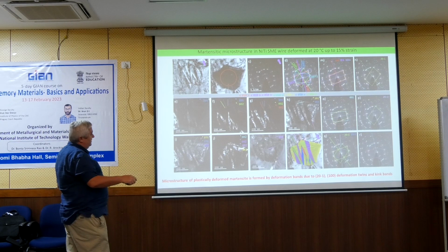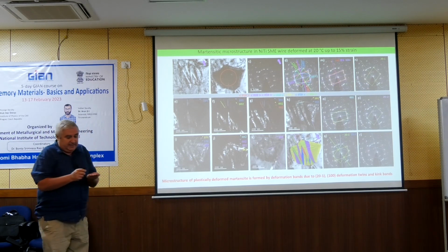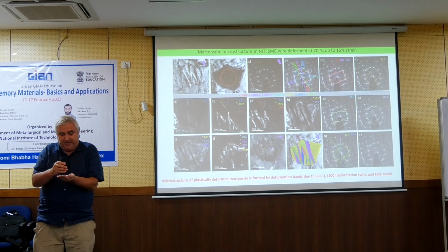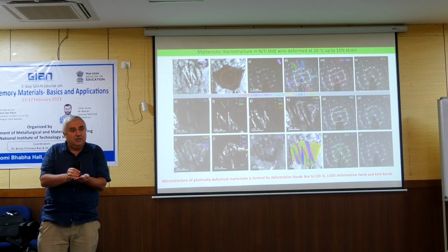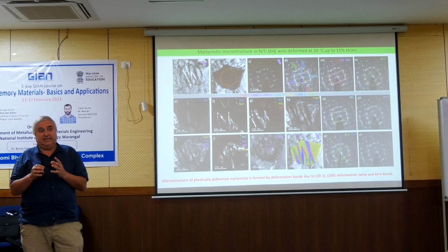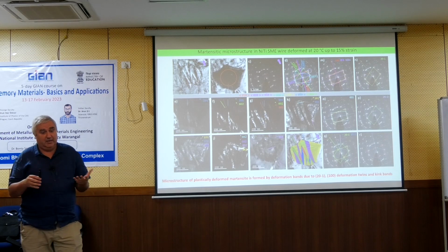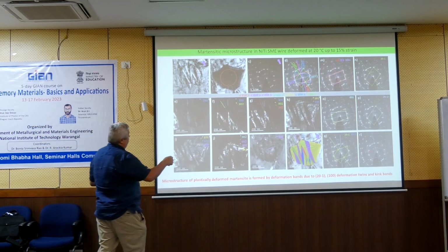So it means that if there are some bands, and there are many bands, the lattice is misoriented in such a way that the 001 direction is aligned with the beam in all these variants. Yeah? So these are very, very special misorientations of the Martensite lattice, which are created by the plastic deformation. The question is why. But now we don't search, we try to analyze this.